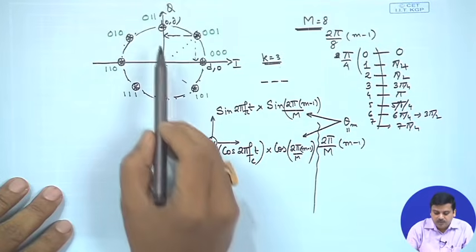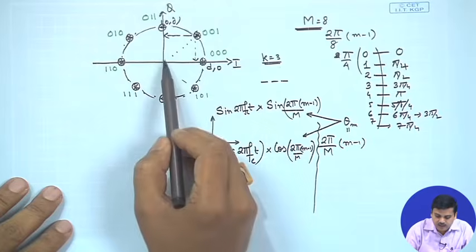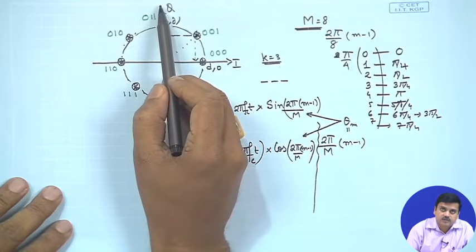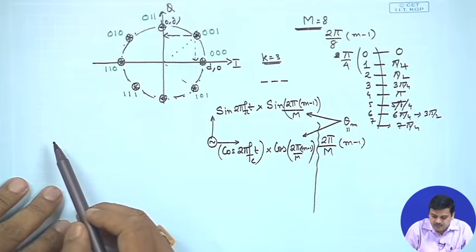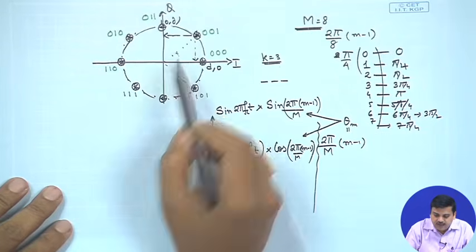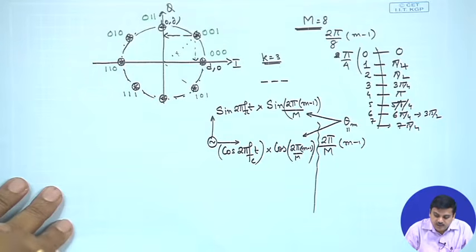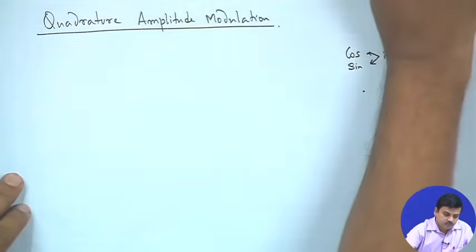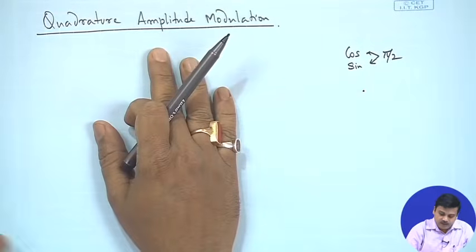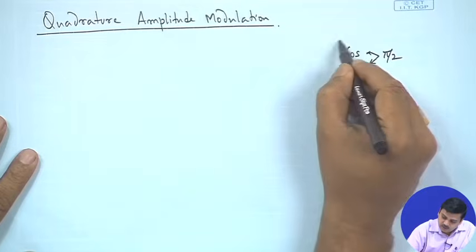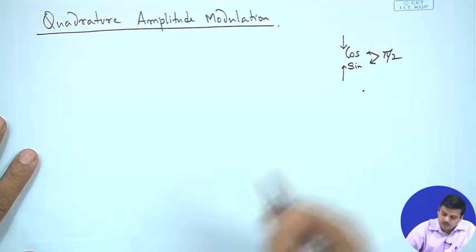That means the amplitude of the I component, the in-phase, and the quadrature phase component. So, if we call cosine the in-phase, then sine is the quadrature phase. They are dependent only on the angle and nothing else, right. Whereas, if we talk about quadrature amplitude modulation, here we are talking about modulating the amplitudes through independent data streams, which is quite in contrast with what we have studied before.